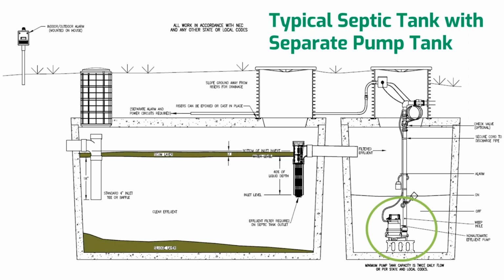With this type of installation, if you're hard piping your pump in, you're typically going to want some sort of stand to keep that pump elevated, just to protect that pump from any sort of gritty material that finds its way through the filter. And speaking of filters, you're typically going to want a filter before that pump tank to protect the effluent pump from those solids.